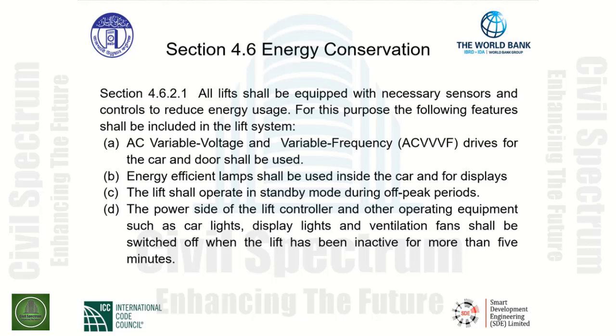Item A indicates that AC variable voltage and variable frequency drives for the car and door shall be used. B, energy efficient lamps shall be used inside the car and for displays. This would produce lower power use, of course, when we use energy efficient lamps. Some of the lamps that we utilize in modern technology are the LED type of lamps.